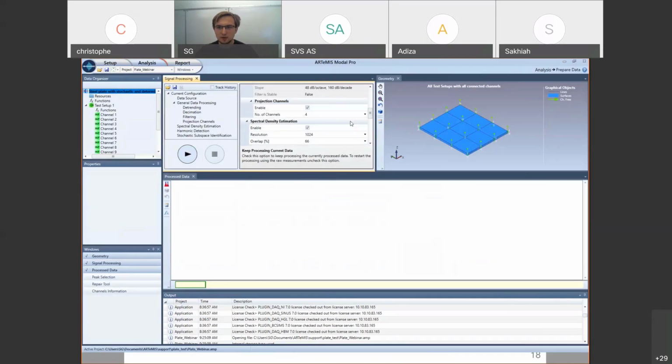First we need to configure, for example, choose the model order. So we can enable the stochastic subspace identification first, and choose model order 80, which should be okay, and don't scale the data with any measure, just analyze the raw time signals. There are several estimators for the data-driven stochastic subspace identification, and the main difference between them is the weighting of the observability matrix, which can result in slightly different model parameter estimates.